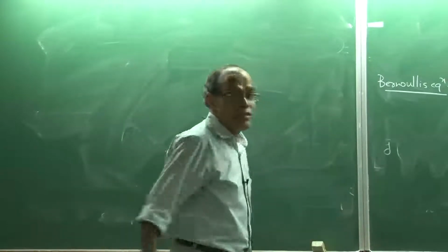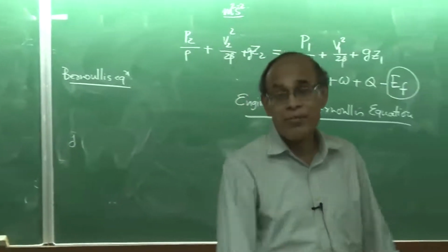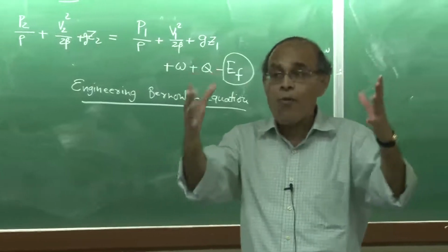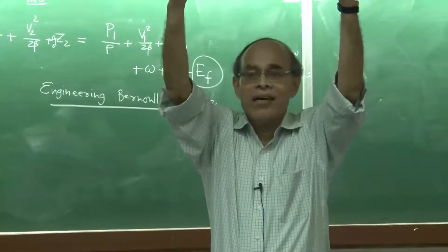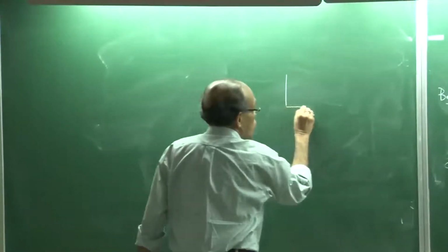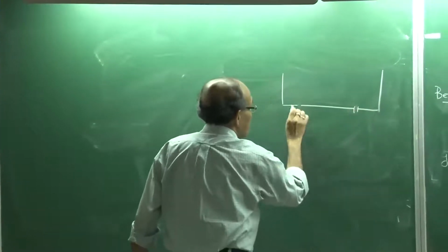All of you know that tun dishes are used in continuous casting processes in metallurgy very frequently. It is a buffer vessel, on top of it the ladle stays, and the tun dish typically maintains a constant flow rate into the mold. There may be 1 or 2 molds, or maybe many.